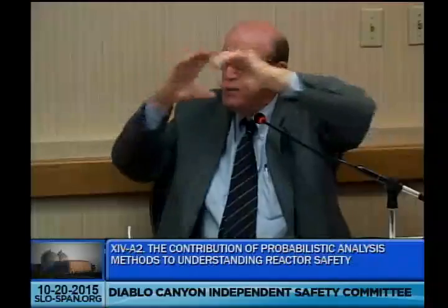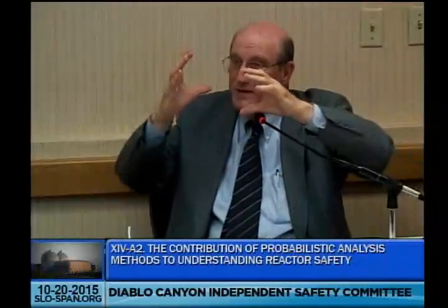And I'll give you the example. One design basis accident is you stipulate that the largest pipe in the pressurized system out at Diablo Canyon suddenly just breaks. We call it a double-ended guillotine break. It's as if the pipe just disappeared and all the pressure flows out that thing. That's called a large break loss of coolant accident. You don't ask how it came about. You just stipulate that it happened. That's the initiating event. The reactor must be designed so that it can keep the core cool when one of those things happens. That's one of the superstructure accidents.